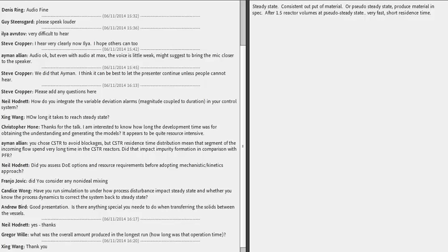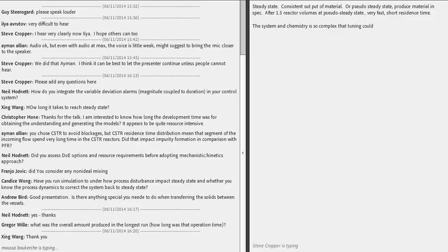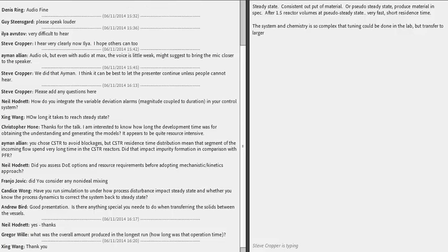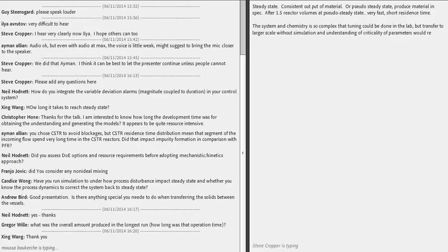We had such a complex chemistry that we could probably have tuned it in the lab and found a nice sweet spot to run it in the lab. After, when you have to transfer it to larger scale, if you don't understand the criticality of the parameters in relation to the characteristic of the reactor, you have to run kind of a DOE at scale to find your sweet spot, and you don't necessarily have the material all the time.